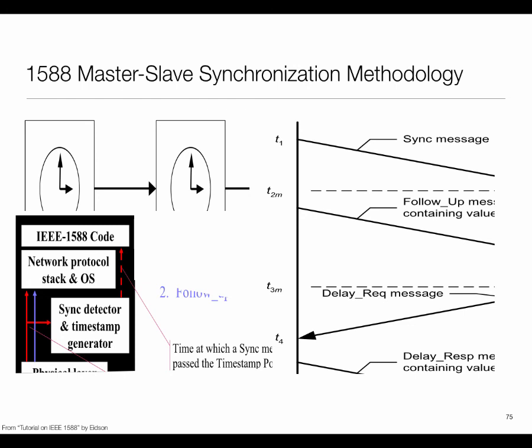At the end of which, the slave on the right-hand side would have T1, which arrives in this packet, T2, which it knows because it measured it, T3, which it also measured, and T4, which arrived in this packet. So it will have T1, T2, T3, T4, and apply the same type of equations, but it's sending 4 messages instead of 2. There are 2 reasons this is happening.